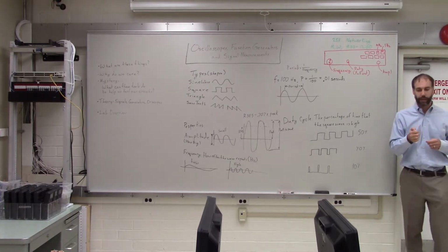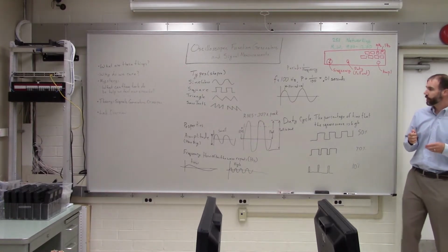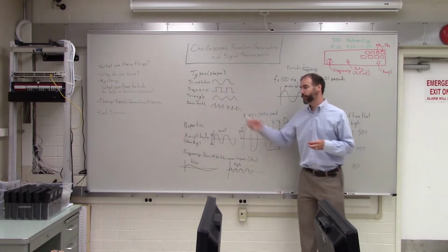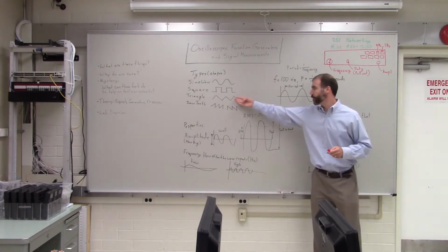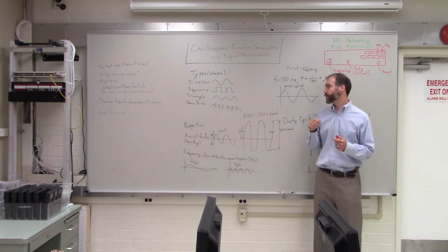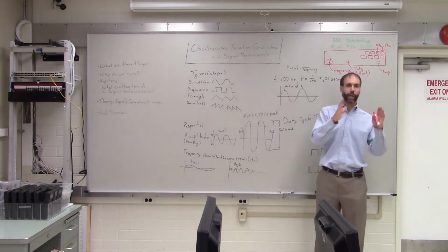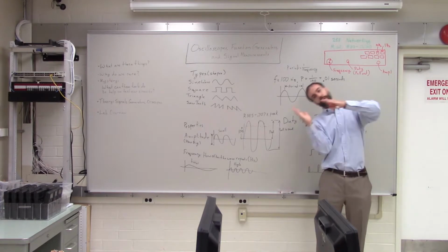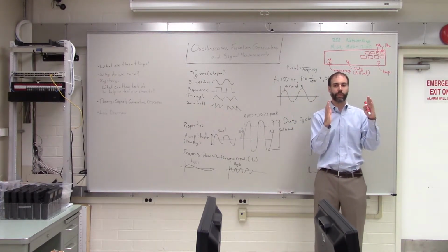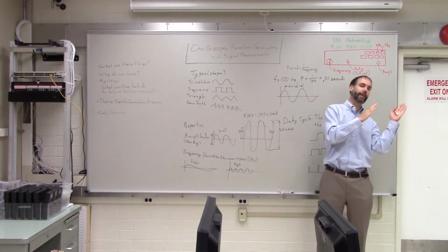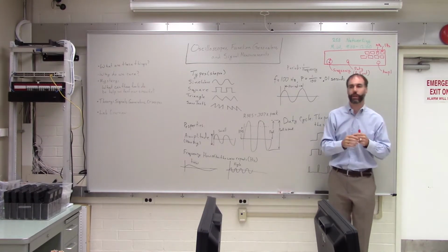Not quite. Actually, that is the key to the sawtooth wave. If you have a triangle wave, and then you pull out the duty cycle, and you turn it one way, it causes the triangle wave to lean over and become a sawtooth wave in one direction. If you turn the knob the other way, it leans the wave the other way, and it becomes a sawtooth in the other direction.